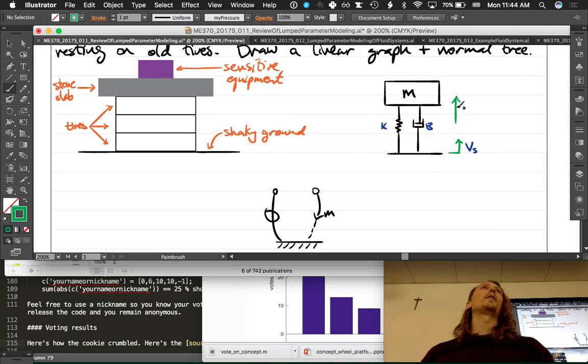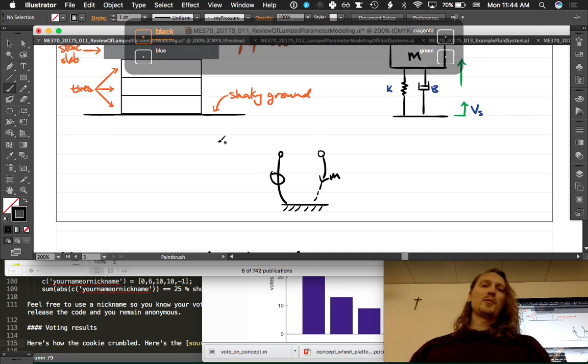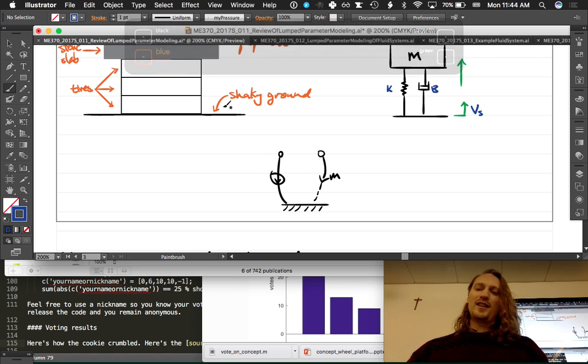Let's define it that way, because our velocity source is pointed that way, and we just don't want to do weird things. If they're pointed in the same direction, we know that an across variable source always points down to ground, which is how I always remember it. So that's our convention. And so there's our VS.